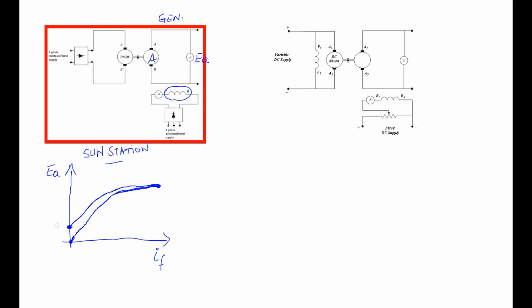This is because of what you call residual magnetism inside the armature. So going forward from zero toward the maximum value, where we have saturation in terms of current and saturation for the generated voltage, and from that point, we go back.